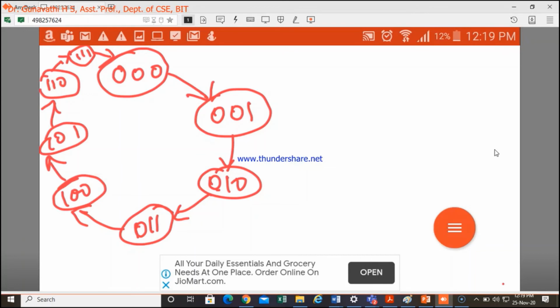So this question can come in the theory: design the counter with any sequence of the count using whatever particular flip-flop they have asked, use that flip-flop and design it. Or else in the lab exam you will have only the JK flip-flop. So now you can start doing this design of the counter for the sequence mod 8. Mod 8 means 0 to 7 it should count. Can you all start writing now?